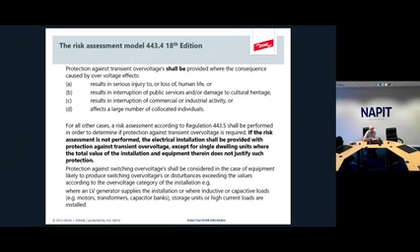Or there was loss of human life, if there was any interruption of public service, and this is a new bit, damage to cultural heritage. So if you're working on any listed buildings, National Trust or English Heritage, you're going to be fitting SPDs to those structures. If there's an interruption to commercial or industrial activity, that's the same from the 17th edition, so nothing new there. And this new one affects a large number of co-located individuals.